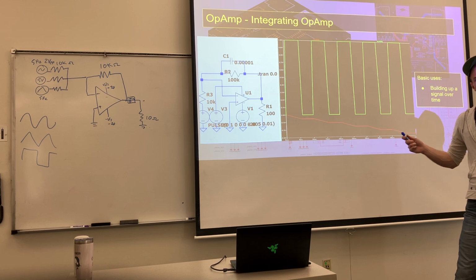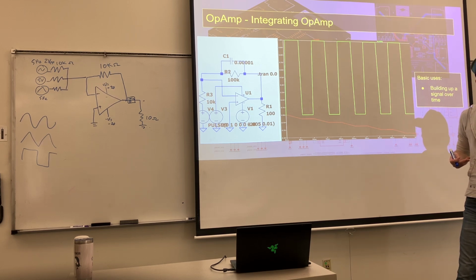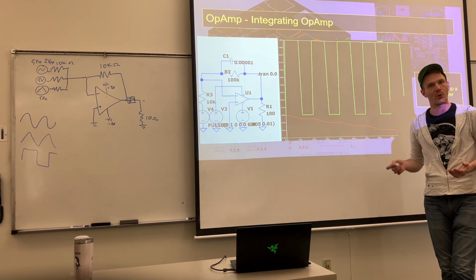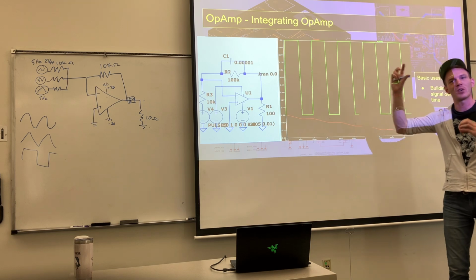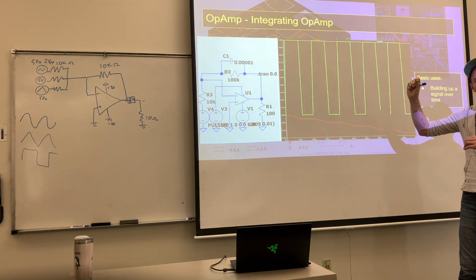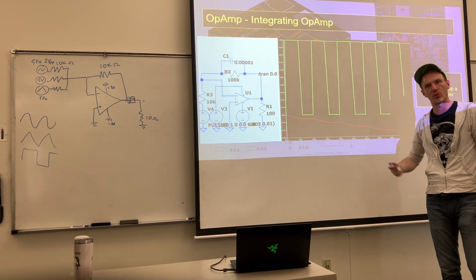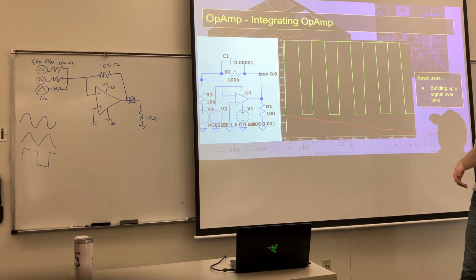The older version would basically take a difference. We use proportional controllers on my submarine a lot for running heaters for spaces, right? You say, it's this cold, I want it to be here, I'm gonna put this much power through the heating coil, and that's gonna heat the room up more. If it gets colder, I'm gonna apply even more energy, right? So you take a difference, you amplify it, you proportionally control it.